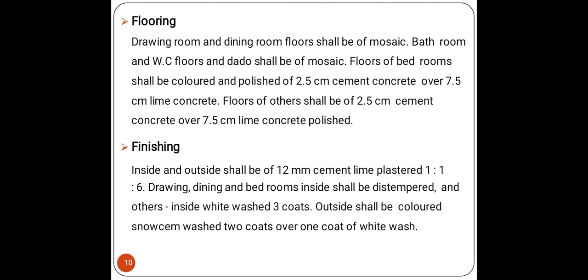For flooring, drawing room and dining room floors shall be of mosaic. Bathrooms and WC floors and dado shall be of mosaics. Floors of bedrooms shall be colored and polished, of 2.5 cm concrete over 7.5 cm lime concrete. Floors of others shall be of 2.5 cm cement concrete over 7.5 cm lime concrete, polished.